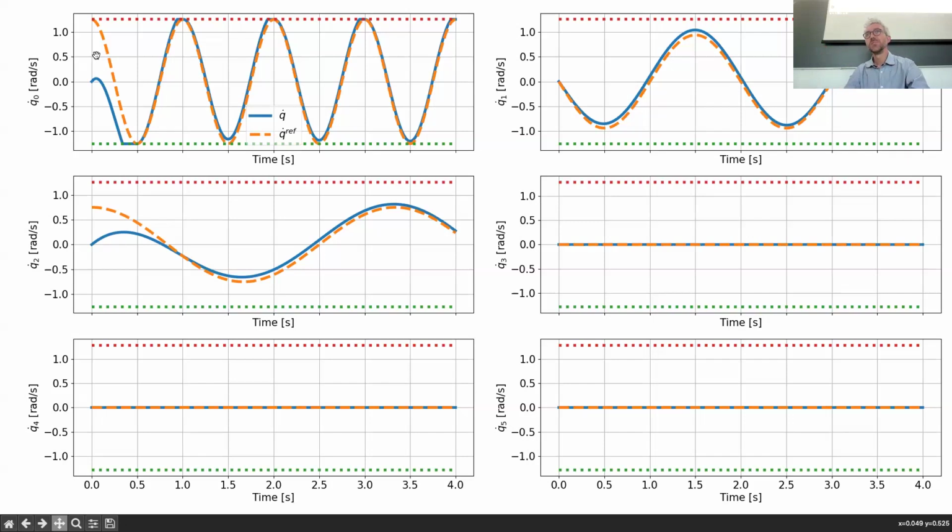Well, that's up to you. But yeah, it's a good practice to start with a 0 reference velocity, I agree. I've carried out several experiments with a non-zero initial reference velocity in my life, so it's not such a crazy thing to do. It's not ideal, but sinusoids are very convenient reference movements for testing your controller, and it happens that the sinusoid starts with a non-zero velocity because the cosine of 0 is 1. So this is something that can happen in practice.